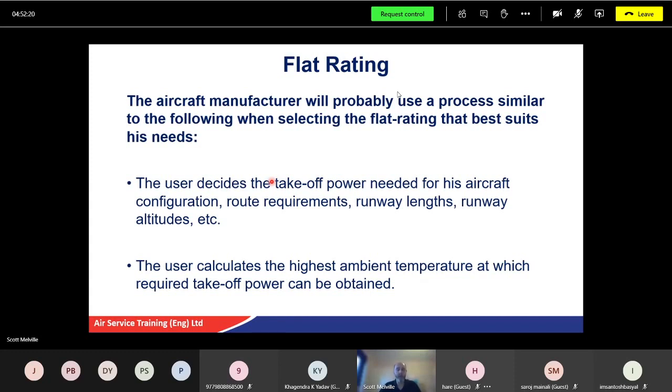Depending on the load, the cargo, the passengers, the fuel, and the ambient temperatures will determine how much thrust that engine can produce as it takes off. In other words, on a hot day, the thrust might be there eventually once it gets the ram effect, so the aircraft must go faster. In other words, it might need a longer runway to get the eventual thrust it requires.